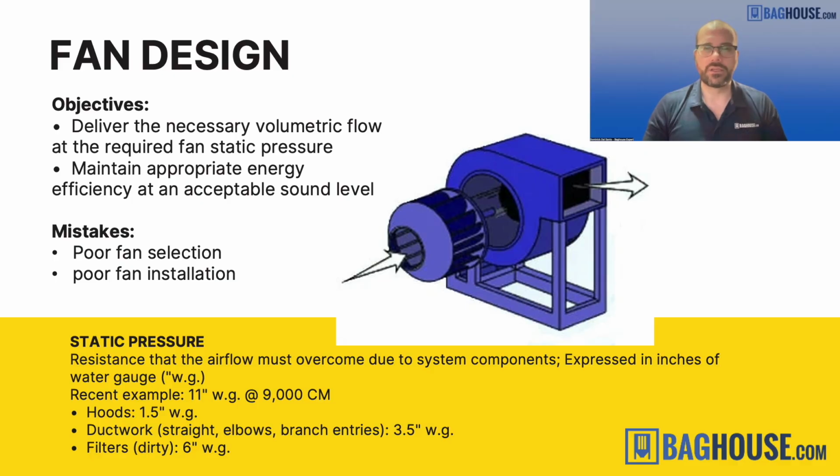But essentially, the differential pressure or the pressure drop, it's the amount of resistance that the baghouse filters make when they're dirty. So for sizing the system, we would say, well, at the worst, the differential pressure is going to get up to 5. And then the cleaning system will come on and clean it down, and there'll be less resistance, right? So what we say is, okay, 5.